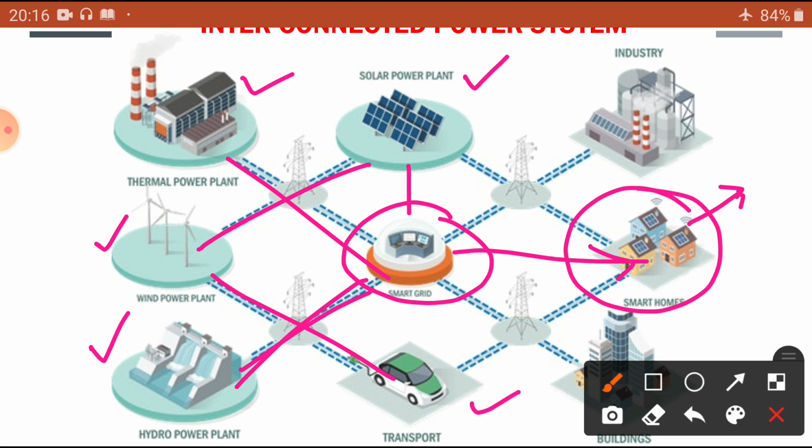In any linear bilateral network having two or more voltage sources, the current through any branch is the algebraic sum of the currents produced by each source acting alone at a time, when all other sources are replaced by their internal resistance. This is known as the simple superposition theorem. Let us see it.